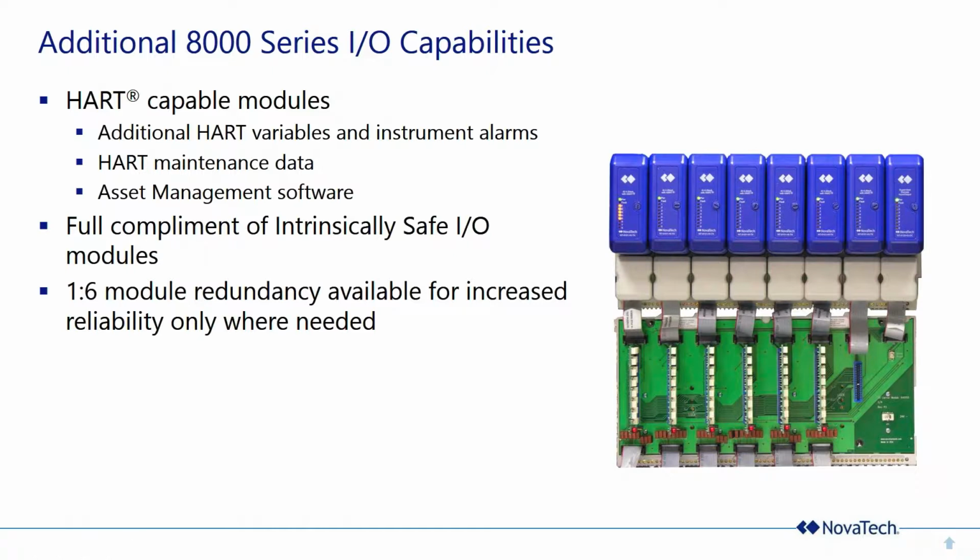If it isn't, it'll copy the configuration from the failed module to module 7. After that's done, it sends a digital output to module 8, which opens a relay, or closes the relay, and flips all the relays on this card. What that does is it sends the signals from the input field across the card into module 7.